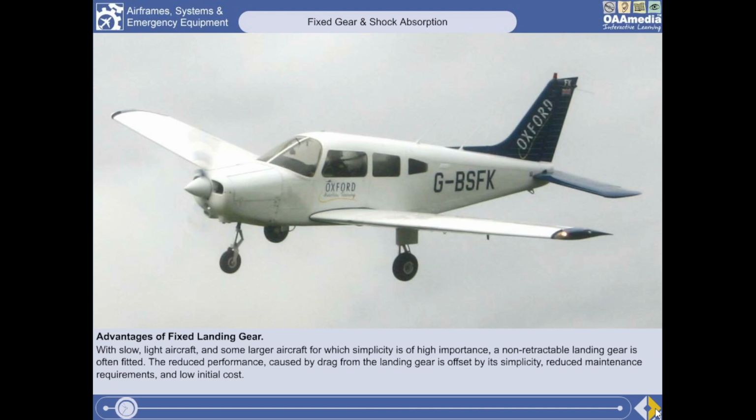With slow, light aircraft and some larger aircraft for which simplicity is of prime importance, a fixed, non-retractable landing gear is often fitted. However, the reduced performance caused by the drag of the landing gear during flight is offset by its simplicity, its reduced maintenance, and also its low initial cost.